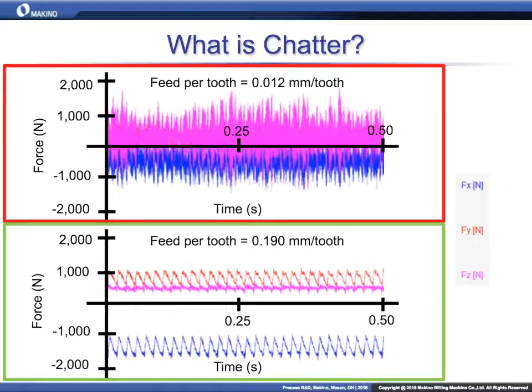You'd actually use the illustration of trying to cut Jell-O. For this example, I like to visualize a block of Jell-O. If you've got a knife and you try to cut off a 1 millimeter thick slice of Jell-O, it's not going to happen. The Jell-O is either going to deform and push your knife off to the side, or your knife is going to slip more into the Jell-O, and you're going to cut a 5 or 6 millimeter cut.